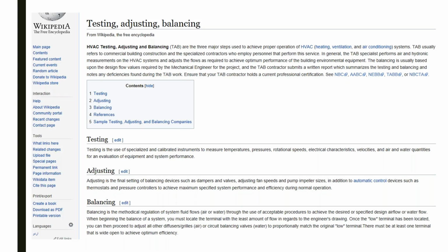Each one of those has to be set up for the minimum and maximum CFM according to the box, because those controls off the shelf don't know where they're going to be installed. They're set up for minimum, maximum, whatever. And so that led to another discussion about how they seem to be using more energy. Slowly but surely, the energy use is creeping up over the last month or year. And also, they seem to be maxing out their air handlers, that they can't keep up.